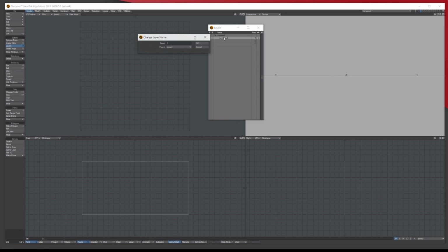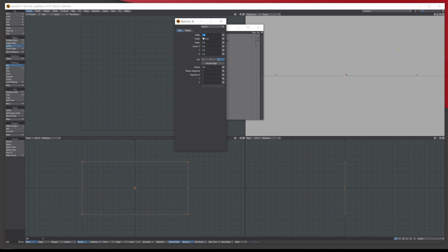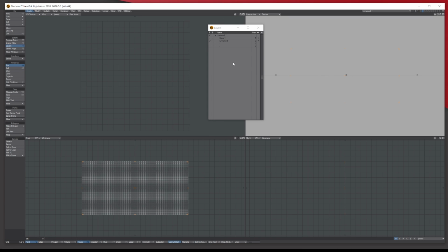Let's just call it brass 1, and then I'm going to another layer here. Once you've done one, I'm just going to go to box, press numerical, not going to drag it out. It'll bring up the default settings from before, but all I want you to do is in the X and Y, let's put 50 and 50, so we've got all these different polys, so we can use a displacement map on it. So shut the actual numerical, spacebar to drop it.